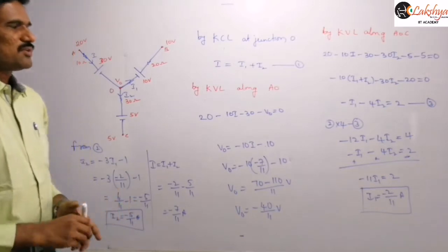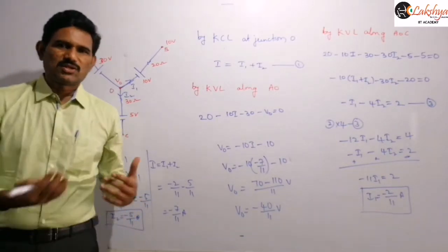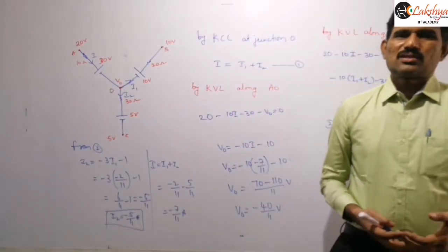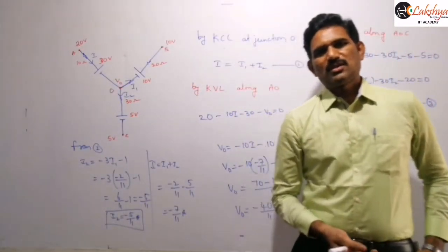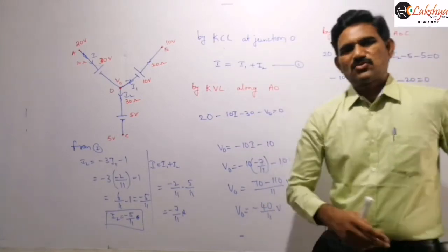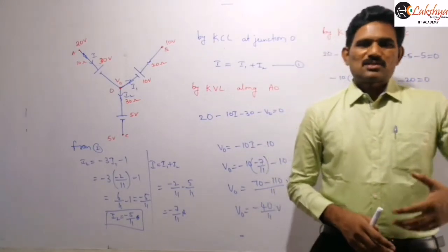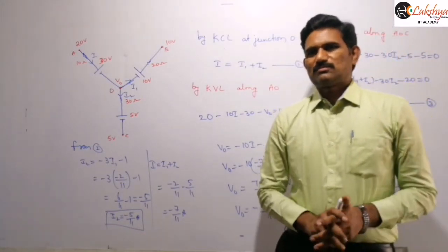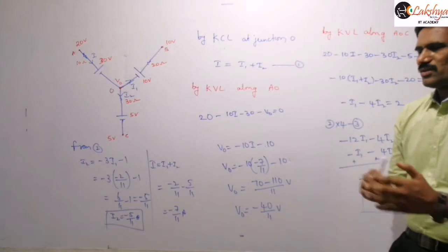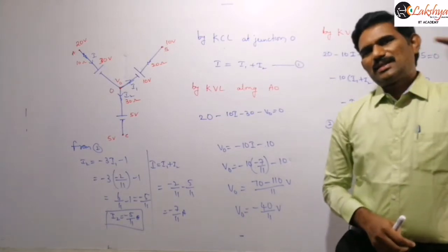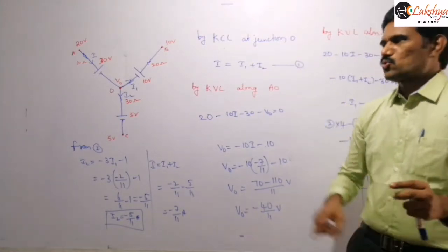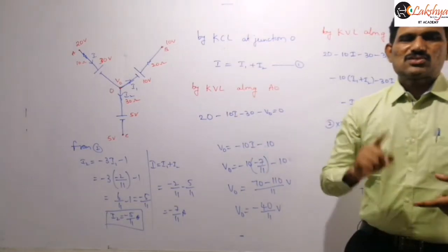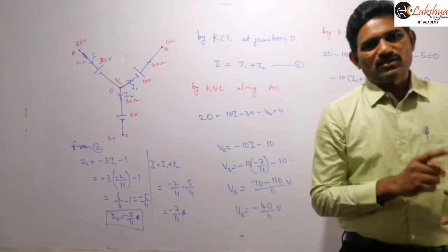So that is the potential of that point V naught. Like that we need to find it when cells are also included. When cells are not there, the problem is very easy, just with the help of Kirchhoff's first law you can solve it. Whereas when the cells are included like this, then definitely some calculation is involved. That is a way of solving that. In the beginning I said another method. The other method is, instead of applying this Kirchhoff law, you need to identify here, first we calculate I1, I2 and I values, right?